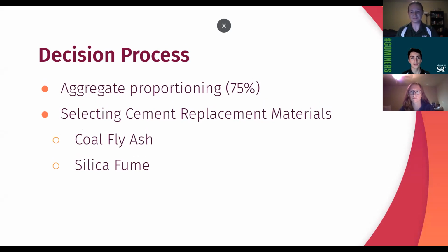So to begin, in our design phase, our team recognized the requirement of having a minimum of 75% total mass of the mix going towards the aggregates. Additionally, however much we include would have to be equal between both cases. Knowing that our improvement depended on cementitious materials, we decided to have the bare minimum of aggregate to have the most amount of cementitious material to replace.